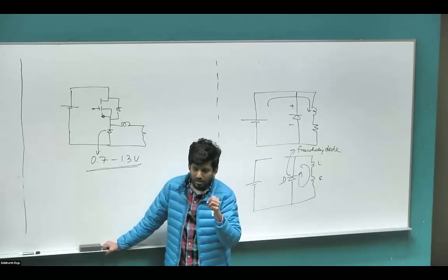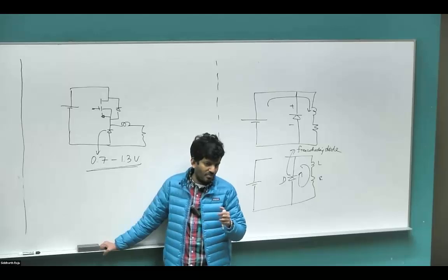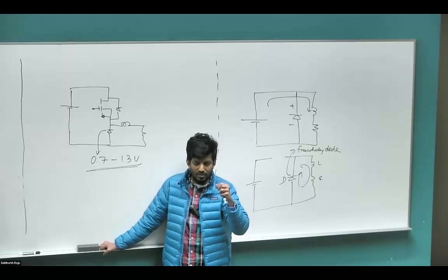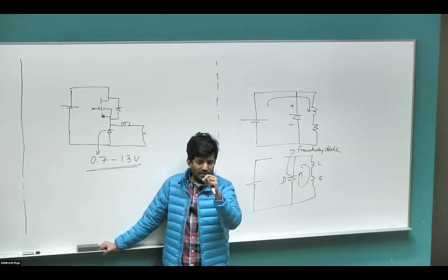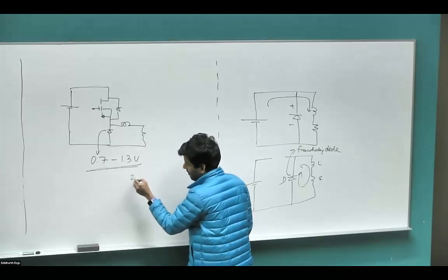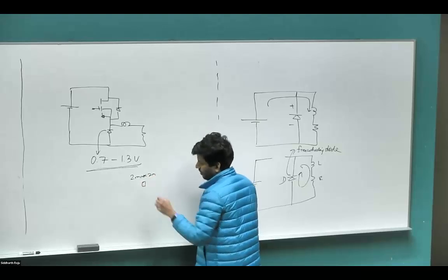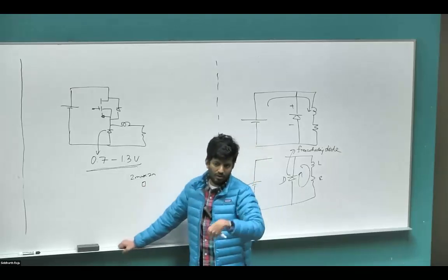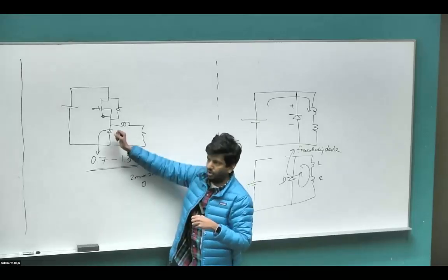And these are tiny, tiny devices. That lamp that we have on the table is a 60-watt lamp. Those of you who have used an incandescent lamp in your basement or something, you know how hot that lamp gets, even if it operates for a short period of time. Compact that all into a tiny, tiny substrate, which is probably 2 mm by 2 mm in size. So the heat coming out of the bulb is going to be concentrated into this particular area. How are you going to take out all of the heat? So when you get to higher and higher current, this structure becomes a problem.